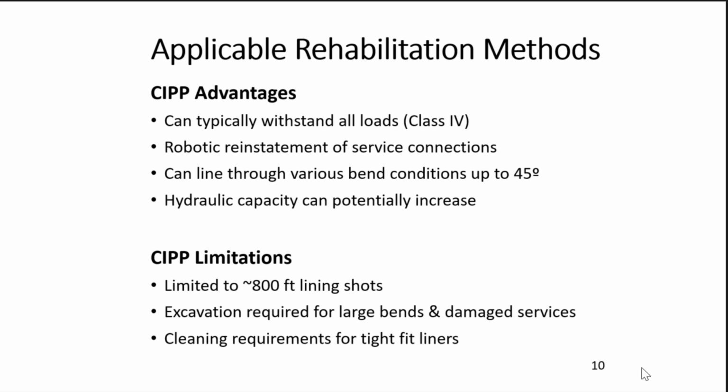Sometimes if there's multiple bends, like multiple weird configurations, which does happen, you may have to add some additional excavation pits, access pits. But in general, they can navigate these liners because they're soft when they're going in. They can navigate relatively complex bend conditions pretty well.